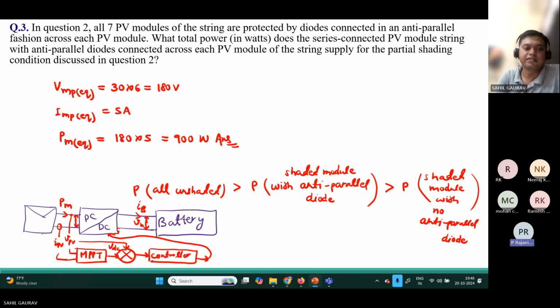If the insolation is more, the output will go high. So how are we fixing the MPPT? Whenever the output voltage is maximum, we make the switch on so that the output goes from the PV module to the load, and whenever it's low, we switch off. Is it happening this way, or how are we fixing the maximum power point?